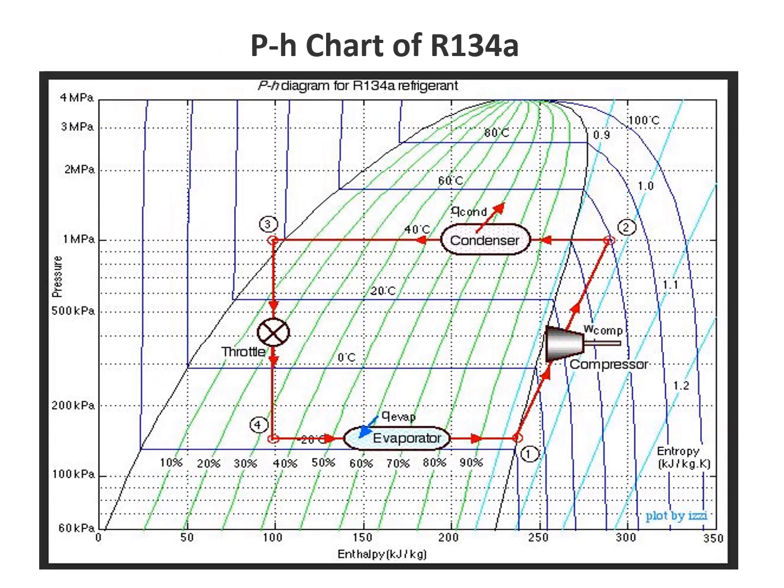And now you see this is the pH chart, which I already told you about, the pressure enthalpy chart. The enthalpy is the main thing which you have to observe in different states, and that is with respect to the pressure. So this is the R134A pH chart. With respect to the refrigerant, we have a different pH chart, depending on what type of refrigerant you are using. Here you see this is the pressure, with different units of pressure, and on the x-axis this is the enthalpy in kilojoule per kg.